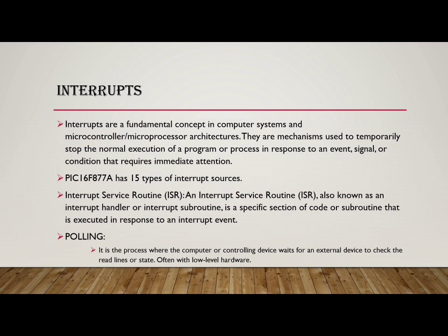Interrupts. Interrupts are fundamental concepts in computer systems and microcontroller and microprocessor architecture. They are mechanisms used to temporarily stop the normal execution of a program or process in response to an event, signal or condition that requires immediate action. PIC16F877A has 15 types of interrupt sources. The interrupt service routine, ISR, is also known as the interrupt handler. It is a specific section of code or subroutine that is executed in response to an interrupt event.